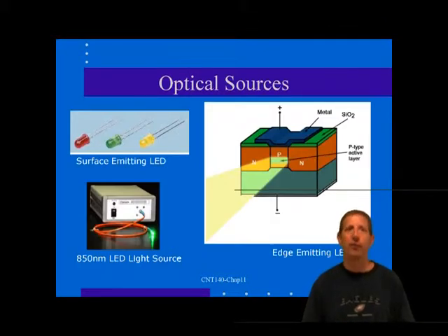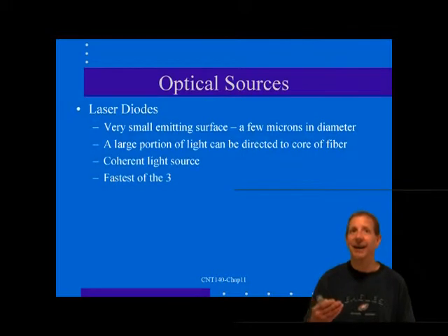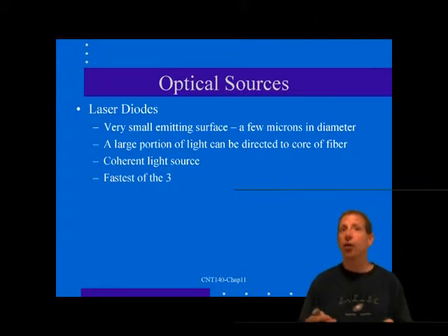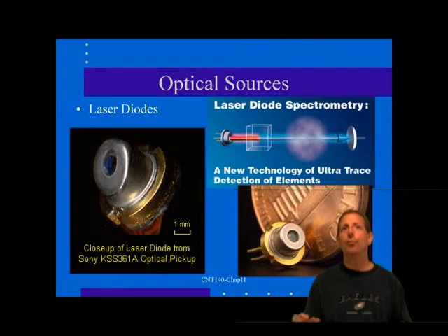Unfortunately, when multi-mode fiber was made in the past, little attention was paid to minor defects in the glass core. If multiple modes are launched into the fiber, a tiny aberration here and there causes little harm because of the other modes or rays of light that would get through just fine. At most, these defects might cause a small increase in cable attenuation.